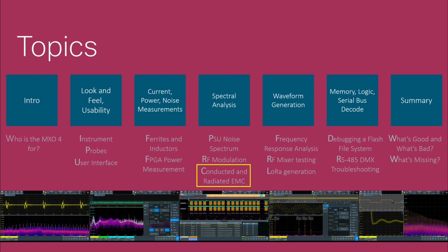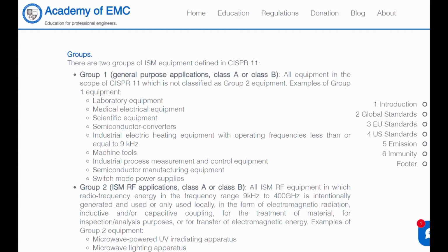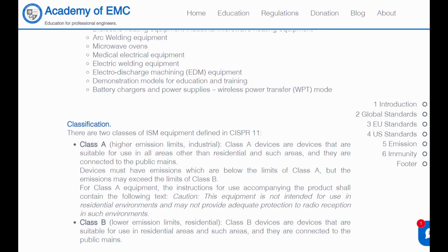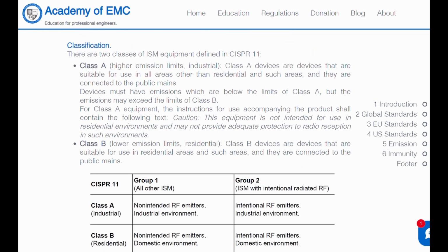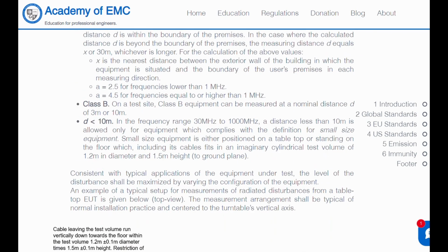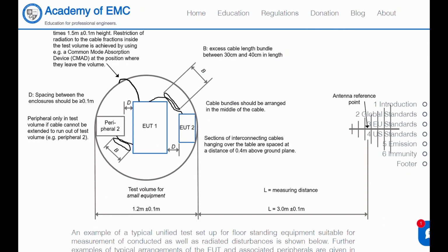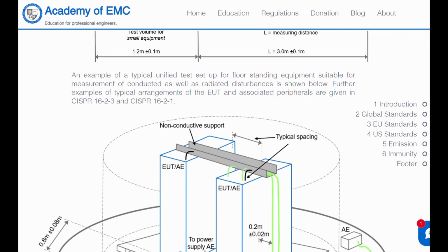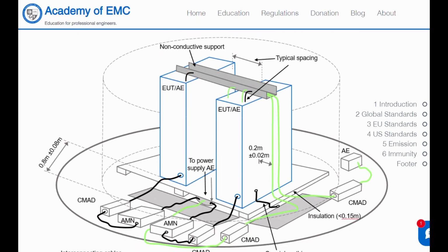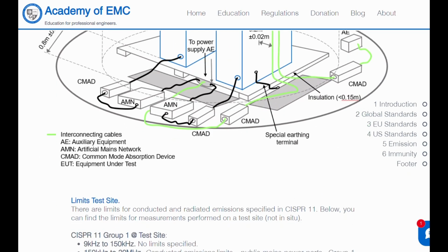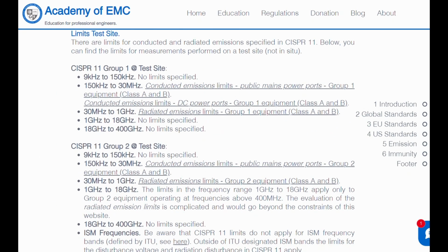I have the 500 MHz MXO model, and there could be emissions at higher frequencies, but often those are a result of harmonics from lower frequencies like clocks, etc. So there is still value in testing, even if 500 MHz is the limit. Obviously, this doesn't help with things like spurious content at higher frequencies, but that can be identified in later pre-compliance testing with alternative test equipment.